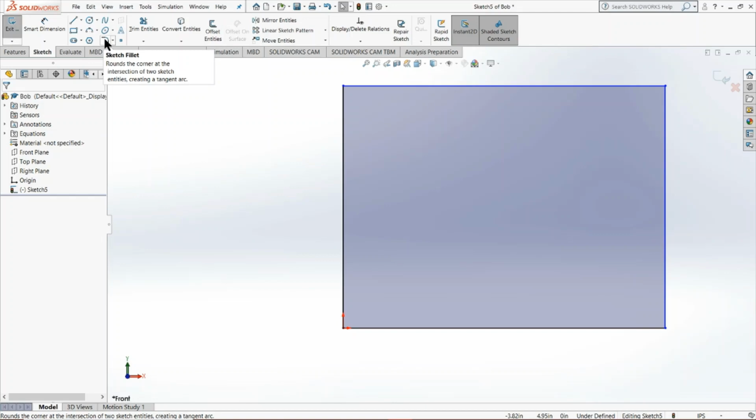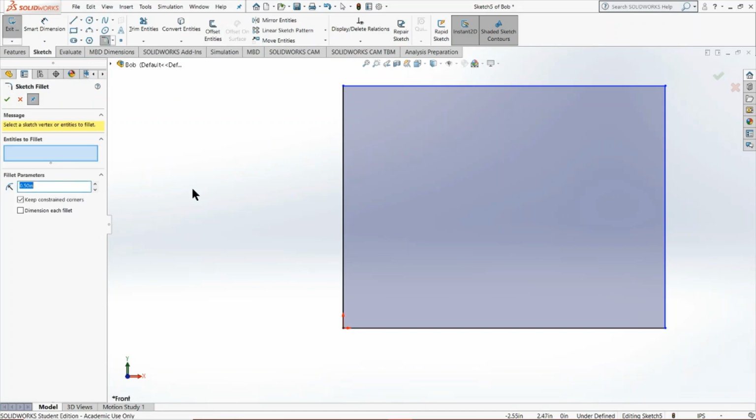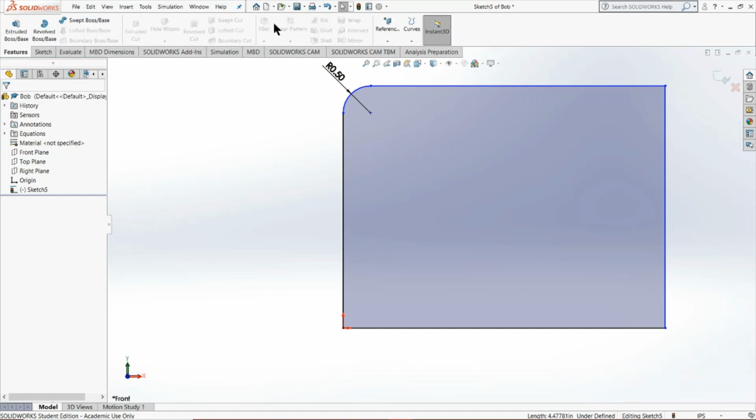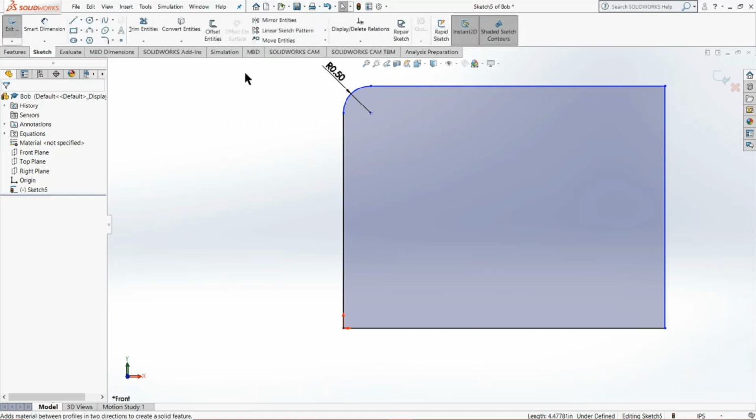functionality of a sketch. More or less for the former point, we have the sketch fillet tool up here. When we click that, rather than having these pointed edges, as you can already see by the preview, it provides us with these rounded, smooth edges for our sketch. Once you accomplish the function, it does that. Now, this is the sketching version of filleting, but there's also one that you could use for features. If you look here, right there, your fillet tool. So don't think it's all done and over if you forget to do that in your sketch.